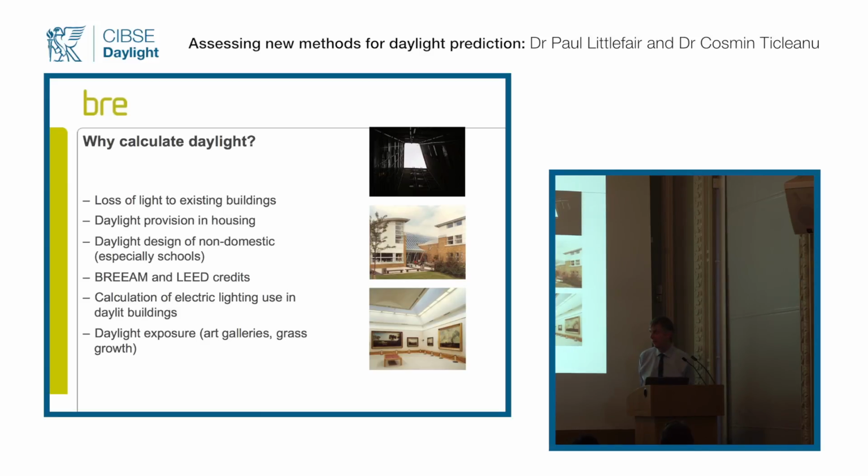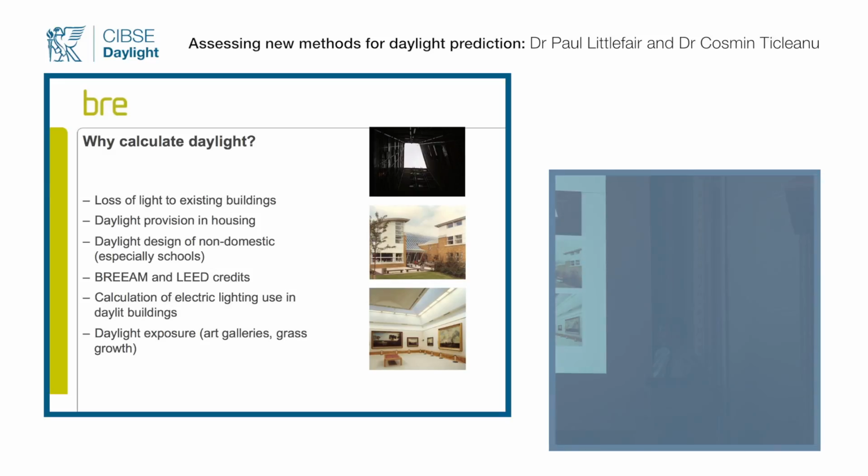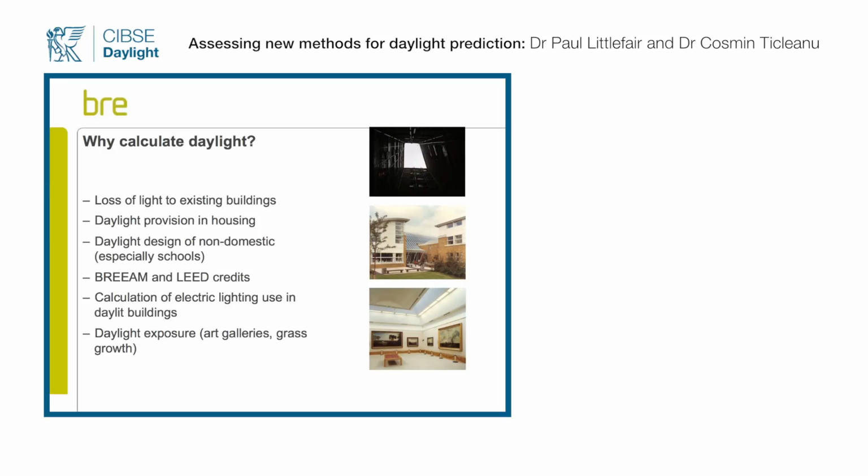And I think that would be a bad thing, because one of the things that the BS does, I mean, it doesn't always give you great daylight, but what it tends to do is to weed out the really sick buildings, the buildings with average daylight factors of 0.1. I'm concerned that with the new European standard, you could get a situation where those people say, well, everything fails the European standard, so it's no worse than anything else.